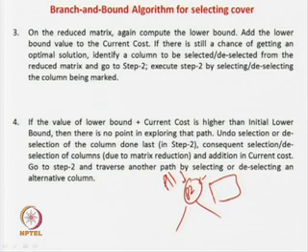Had it been the terminal case, you can find out by taking P1 and the essential columns what is the cost. If the cost is less than the lower bound estimate, then you are very good, you have reached optimality and you can stop. But if it is not the terminal case, then again on the reduced matrix you apply the lower bound and see if the lower bound is, say, 3, that means in this reduced matrix you need at least 3 prime implicants to cover it. Then you add it to the current cost. Say current cost was 1 over here.